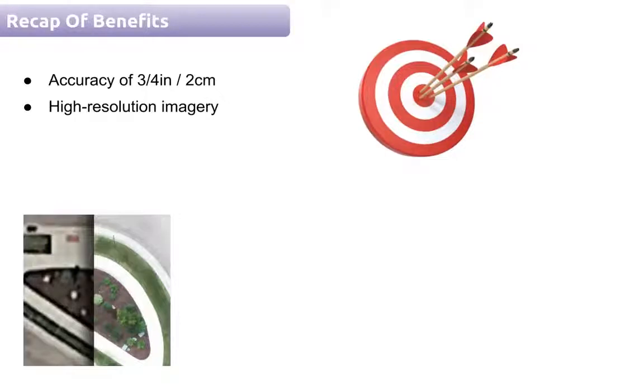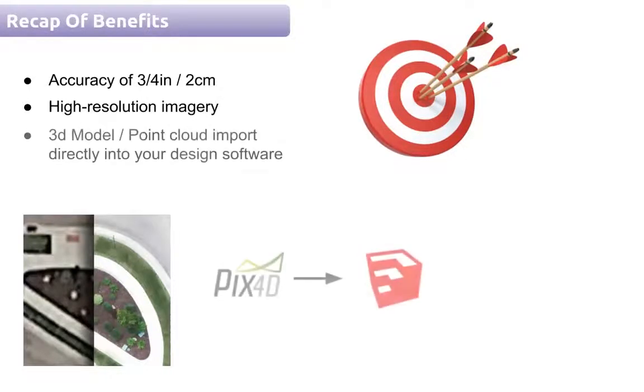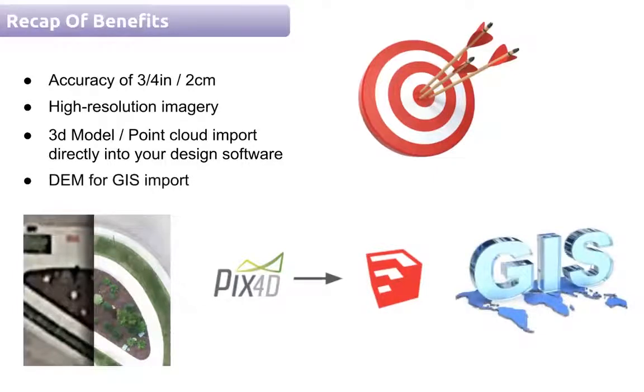And then you get the 3D model and the point cloud that you can import directly into your 3D modeling program to start working with, which is a great time saver. Again, you're not going to get a perfectly polished model, but it provides an excellent framework around which you can quickly create a highly accurate model. And it's also going to generate a DEM. If you work on a large site and want to take your information into a GIS, DEMs can also be exported.